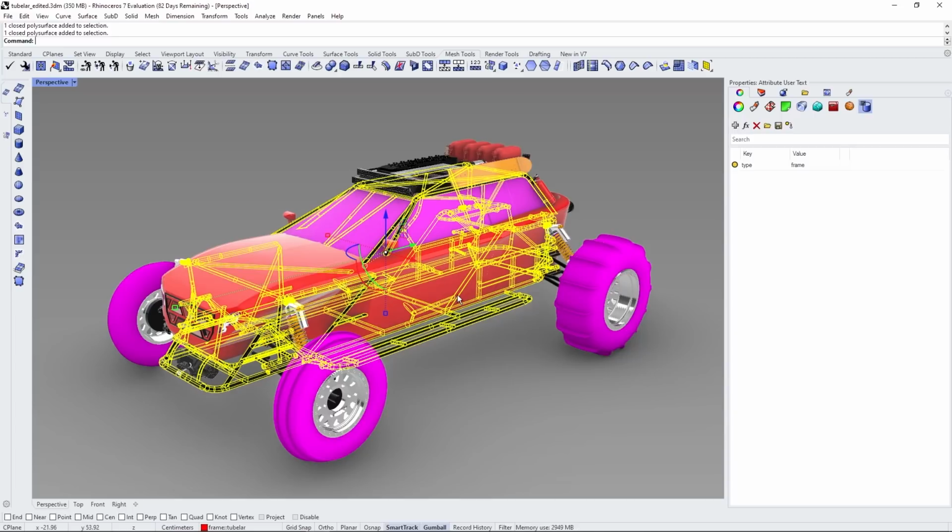And I'm going to be using that metadata to optimize the model because right now it's actually pretty high on the mesh count. It's running around 600 meshes. So we're going to be merging all those meshes together using the metadata. And I'll show you how that's done inside the tool when we get there.